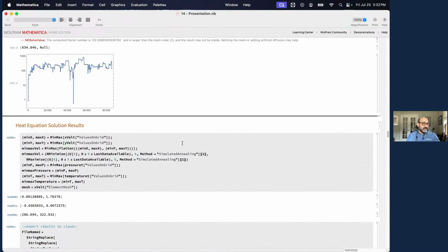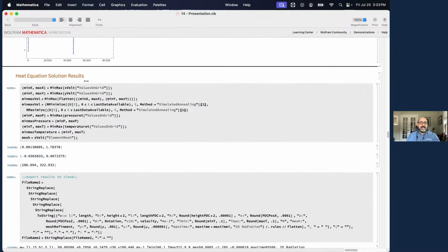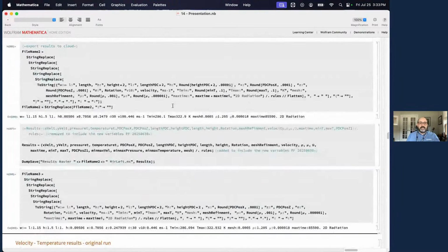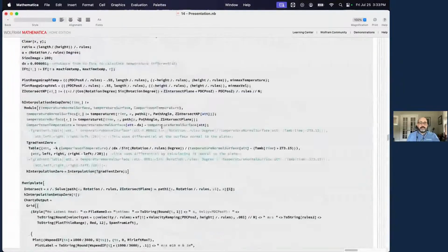If you have more than 3,000 elements, it's going to multiply that by the number of elements you have. So if you have 3,000, 1 day. If you have 6,000, 2 days, etc. That's why the optimization of the element is so important when you have complex problems. Okay, so again, I take my solution. I don't want to be wasting any time, so I take my solution so I can reuse it later.